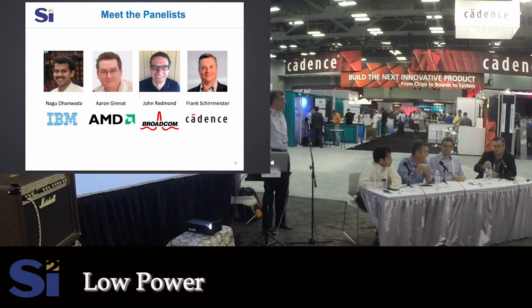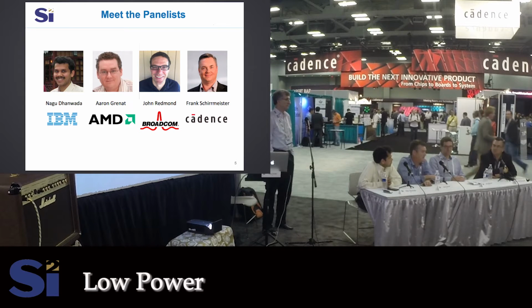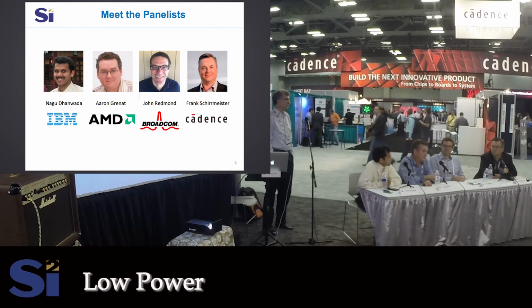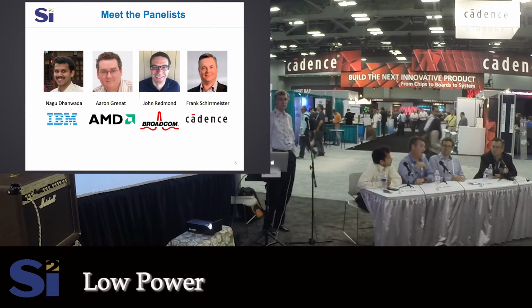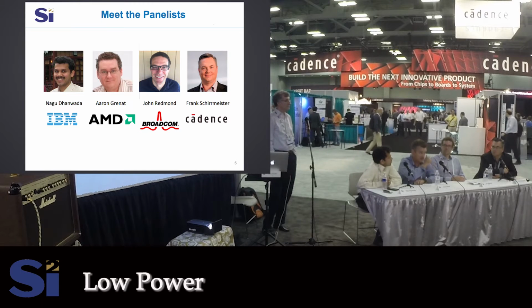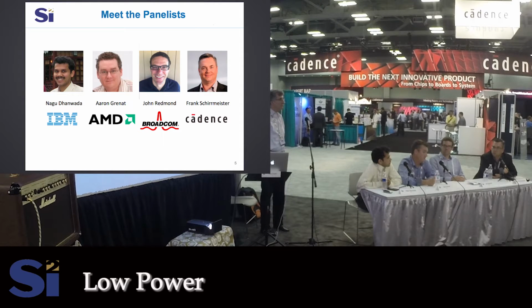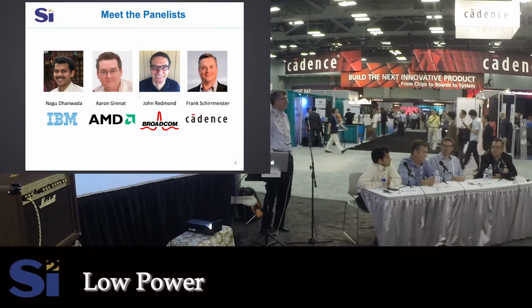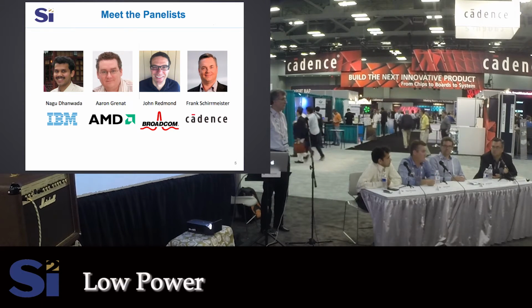Because we do know there's a gradient, and that 30C number is not that different than what we see, maybe a little less. But the point is we guard band for it, and if the question is, do you see value in fine-grained thermal sensing? The answer is yes. If we can make a reliable one, that would be very useful, because not only would we not have to guard band for reliability purposes, we know what our true hotspot is, but we also could remove guard bands for our power limits inside of our power management firmware that we're reading with thermal sensors.